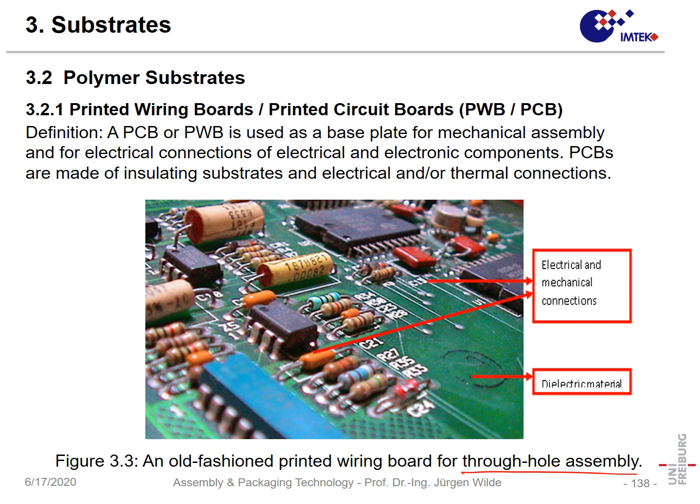It's a through-hole assembly, and we can see here we have the printed wiring board. It's similar to what already exists. The components all have pins. These pins are bent in a way we can plug these pins into holes in the printed wiring board, and then we solder these. So all of these here are soldered joints.